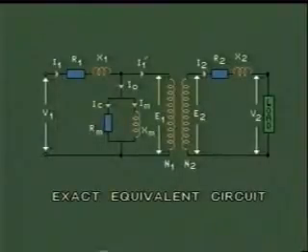You can see from the diagram, I1 dash is the additional current drawn by the primary winding to counterbalance the secondary MMF. That is, I2 into N2 is equal to I1 dash into N1. Now the sum of I1 dash and I0 is equal to the total current drawn by the primary winding, that is I1.